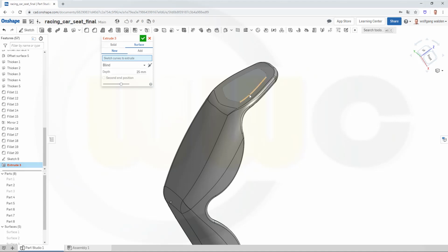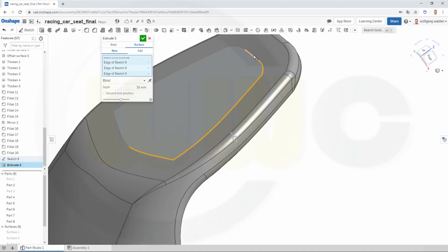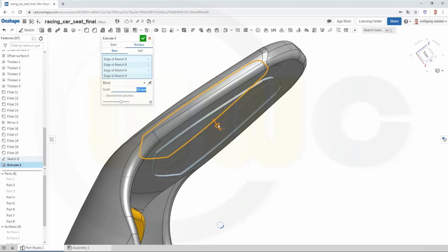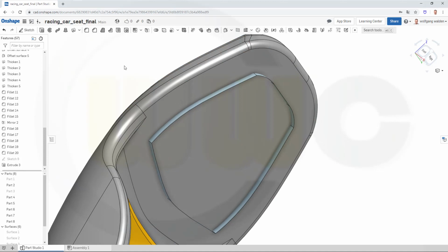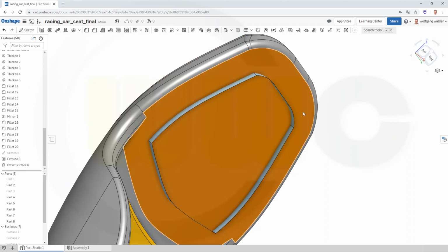Surface sketch goes to this sketch. The other way around. Select them. Okay, that direction, maybe 40 should do, and confirm. Then make an offset surface from this one with 0 millimeter. And now I could split that face with this one.